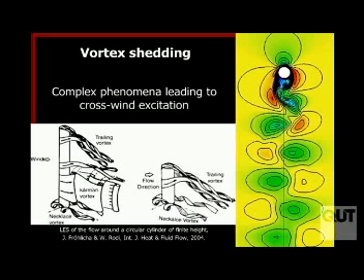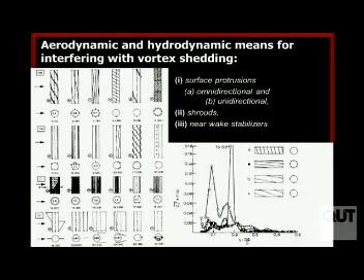And the peak of that is typically at the Strouhal number, or the frequency of vortex shedding. And we need to avoid that if we're going to eliminate motion. So a lot of my wind tunnel colleagues have spent a lot of time looking at a whole range of different ways. Here are just cylinders, because if you think of tall, slender cylinders, the classic example is chimneys.